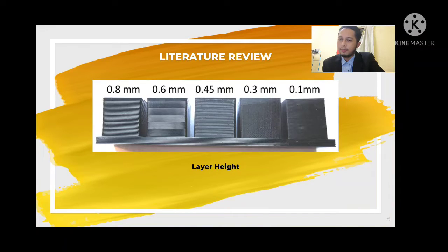What is layer height? Layer height is exactly what it sounds like, the exact height of each layer of plastic extruded, cured, or sintered by a 3D printer. This setting is adjusted through a slicer program and has many more effects on the final print than one might think at first. Used properly, this setting will increase your print speeds, resolution, and smoothness.